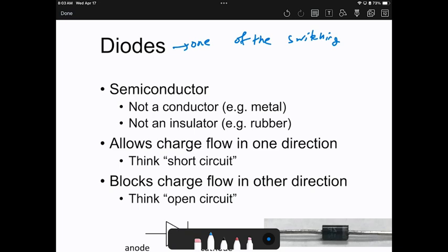That switch, we don't mean the normal switch, which is on-off by yourself. We need to have a fast switching. Fast switching element means that the element that can be turned on or off maybe 1,000 or 100,000 times per second, which is, for example, 100 kilohertz, or 10 kilohertz as 10,000 switching times per second. And there is no way to do this using our hand. No matter how fast you are, you cannot do it manually. The only thing that you need to do is using software switching, or using electronic switching.